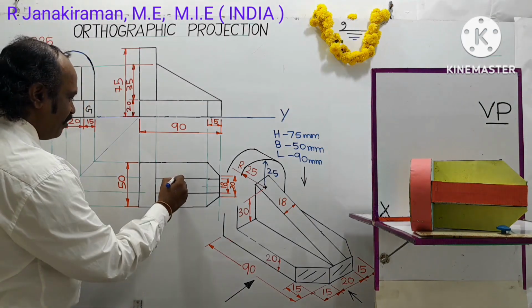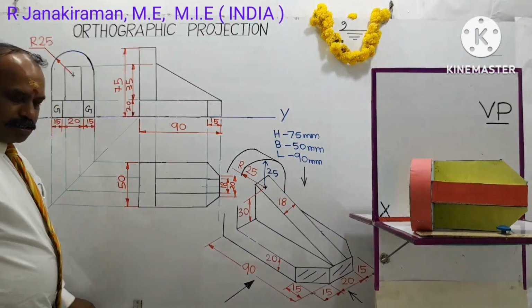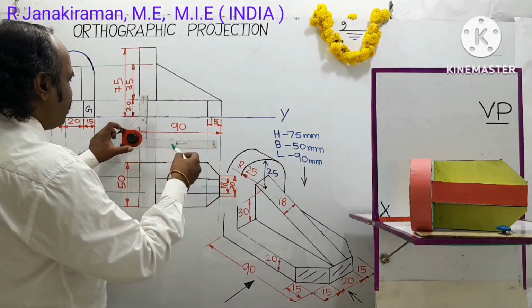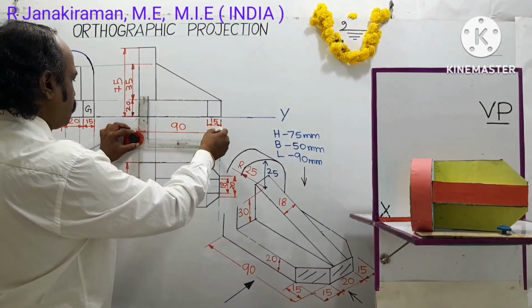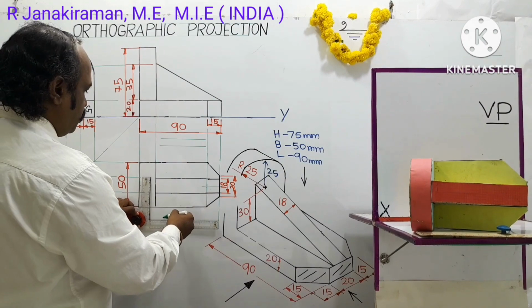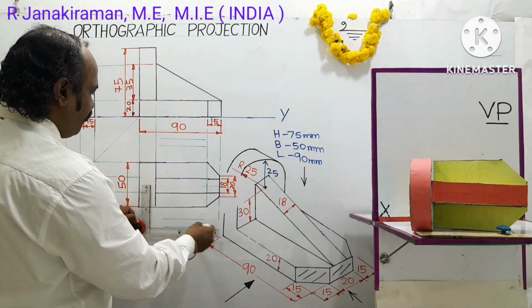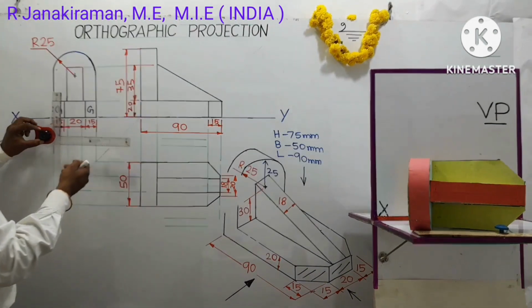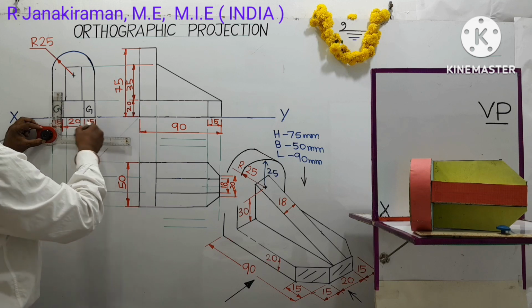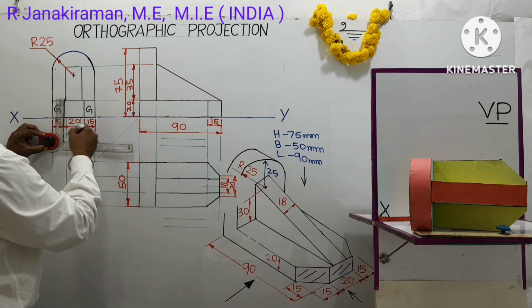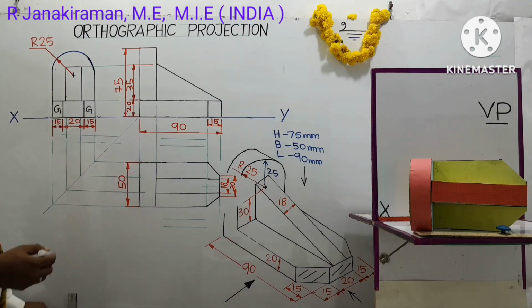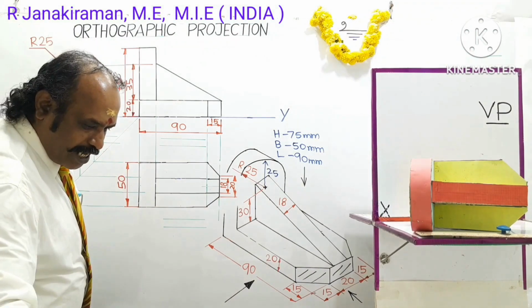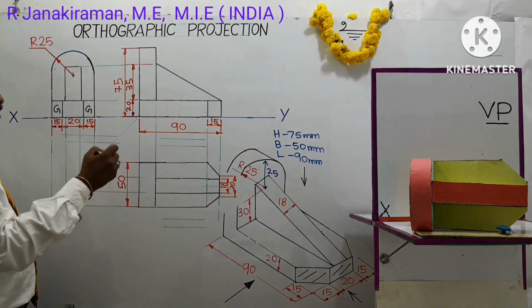So let us write the names of the diagrams. Draw guidelines for uniform height of letters. The top view shall come exactly below the front view, that you have to understand. Writing work should be carried out using an HB pencil itself, so it appears dark.